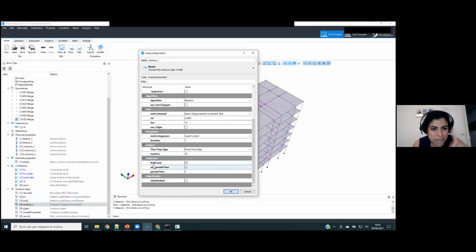Okay, so this is quite complicated. Now OpenSees has the concept of time. Okay, so the time that you see into an analysis is called pseudo time, because sometimes it refers to real time. Sometimes it is not a real time. That's why it's called pseudo time. So for example, in dynamic analysis, it is the real time. In static analysis, it is called pseudo time because actually it is the load factor.